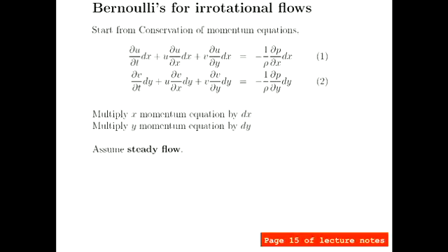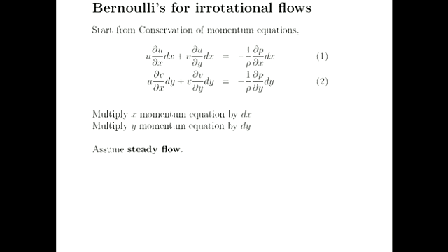And then I also assume that we've got steady flow, just like you did with your previous Bernoulli's equation. So there's nothing unsteady with that half-Rankine body that we've been looking at, right? Nothing's a function of time. I'm not changing the flow or the location of the source as a function of time, so it's purely steady in time.